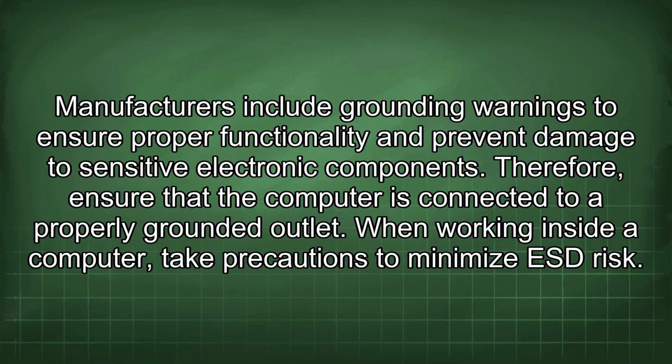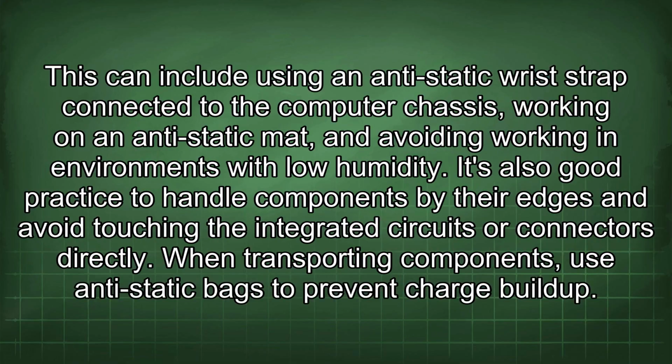When working inside a computer, take precautions to minimize ESD risk. This can include using an anti-static wrist strap connected to the computer chassis, working on an anti-static mat, and avoiding working in environments with low humidity. It's also good practice to handle components by their edges and avoid touching the integrated circuits or connectors directly. When transporting components, use anti-static bags to prevent charge buildup.